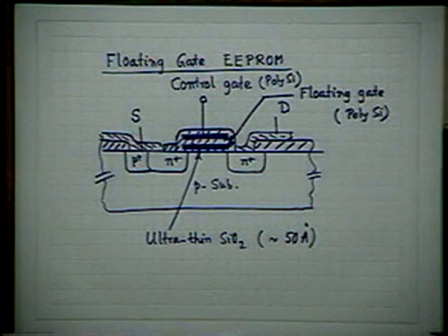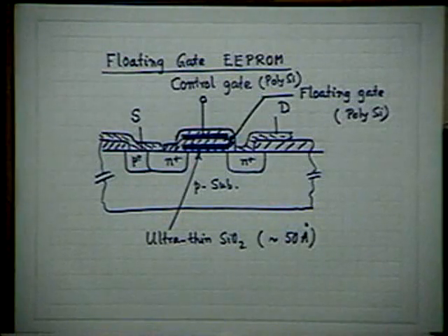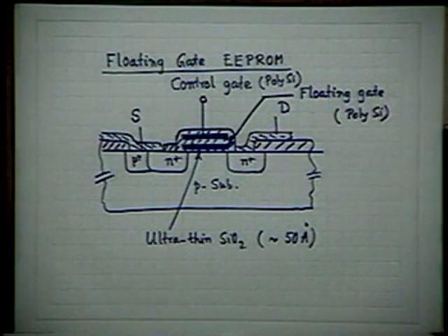This is what is known as floating gate EPROM, which is very popular today. In all EPROM technology, whatever you are seeing, commercially available products, they use this floating gate EPROM. Again, the problem of space, all these things are that they never expect that EPROM will have a higher density than a PROM. PROM is very dense. That is why in calculator chips, most of the stored data are kept in ROM, because calculators are used in billions. So one can produce such ROMs in billions. There is a very good market for it.